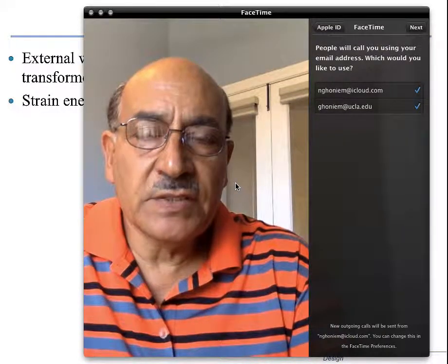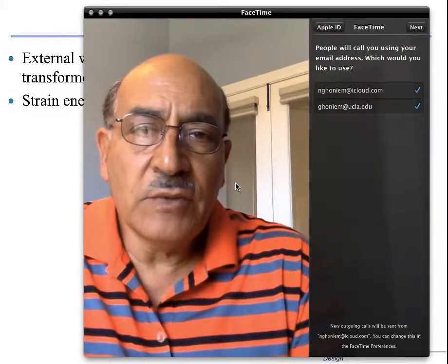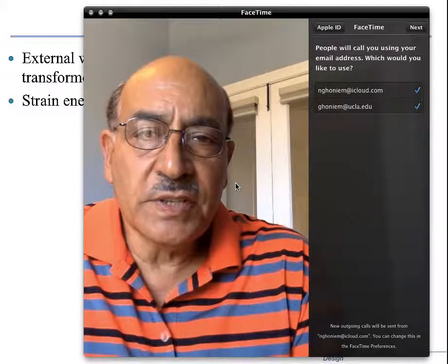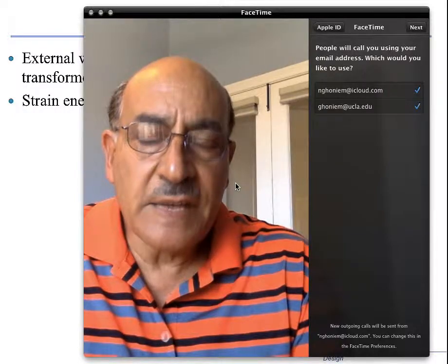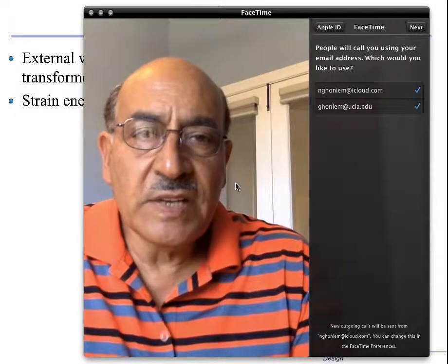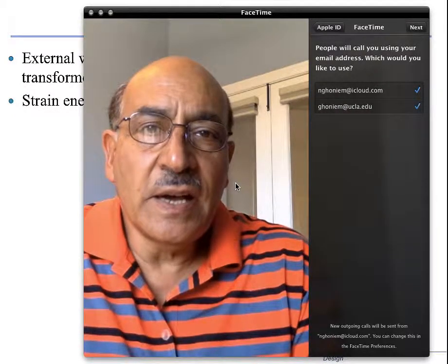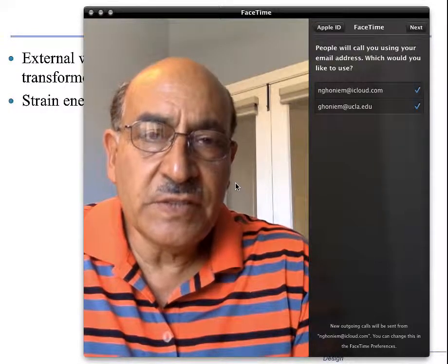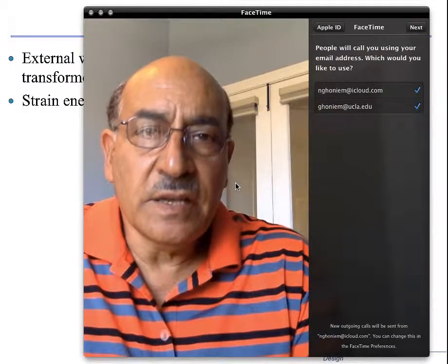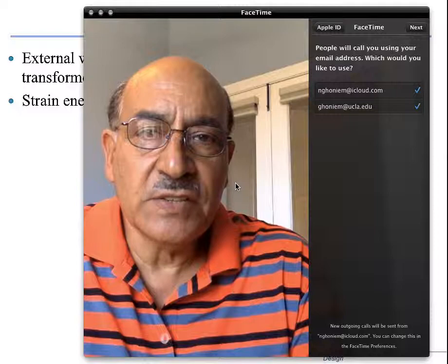In this lecture, I'm going to first explain how we would find out the elastic energy stored in members under tension, bending, torsion, and shear. Once we figure out how to do the calculations for the energy stored, there is a method that we can use to utilize the calculations of energy storage in finding deflections and rotations of beam.